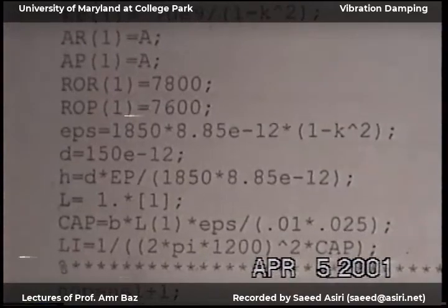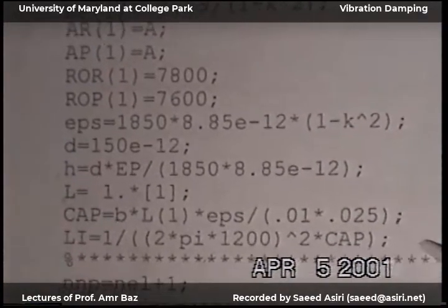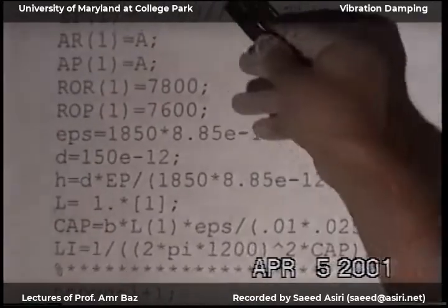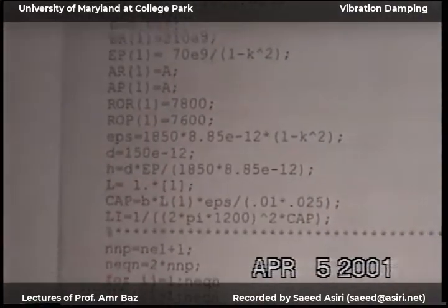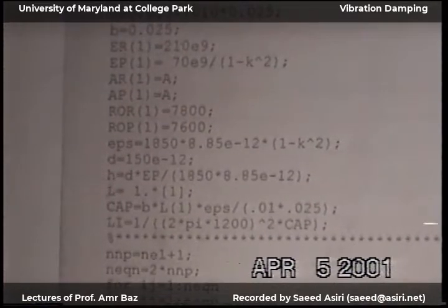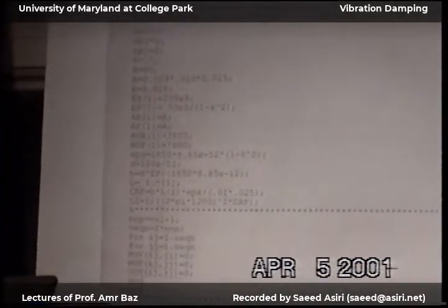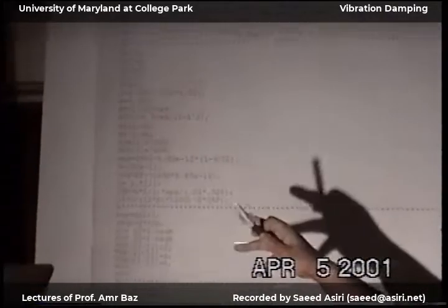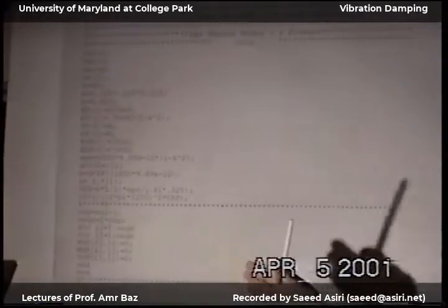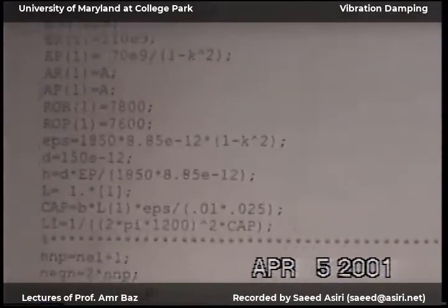And then now, I used exactly the same tuning parameters as the previous circuit. The same inductance and the same resistance. And then now here, I initialize all the matrices as zeros. The stiffness overall, the mass overall, the damping overall as zeros. And then now I say, this program you can modify very easily if you have any number of elements. And some elements will be plain rod, some elements can be rod with piezoelectric on it.